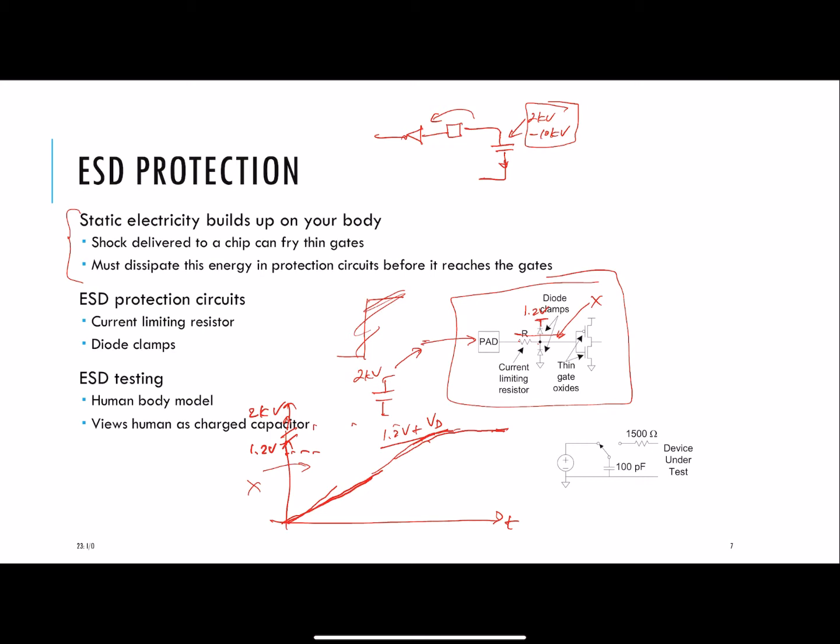The idea is you limit the actual current to a value with a resistor, and resistors aren't going to blow up. It's really mostly gate, transistor gate capacitance and stuff that are at risk. And so you want to limit the current that you have to get rid of, and you also want to slow the rise time of it, so that basically gives your clamping circuits time to discharge that electrostatic voltage. Okay, so this is very basic. Things get much more sophisticated than that, but that's a pretty basic thing. You'd actually see these structures, and I think they're pretty effective.